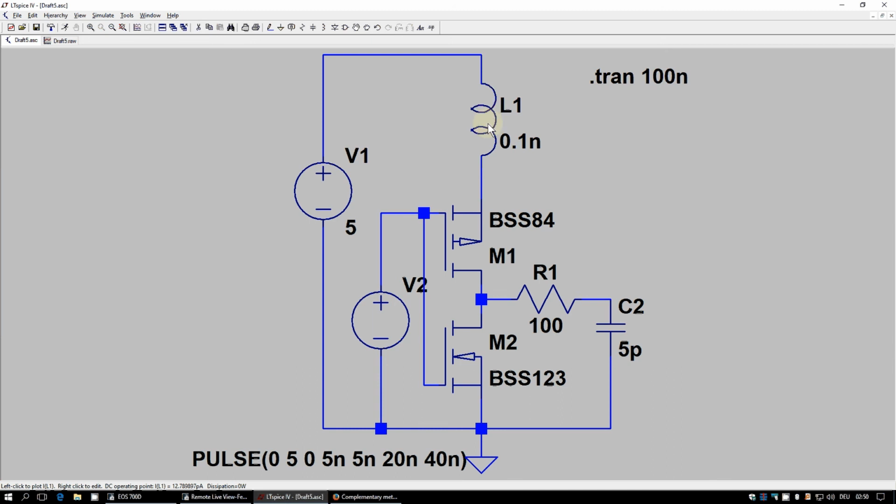And so what we want to know is, first of all, how does our more or less ideal square wave at the input of our CMOS pair look at the output, or better said, at the next input of the next gate? What is the current through for charging here? And these current spikes, of course, transfer to current spikes here on the supply lines. We take an ideal ground and we only look at what happens at VCC, at the positive supply voltage.